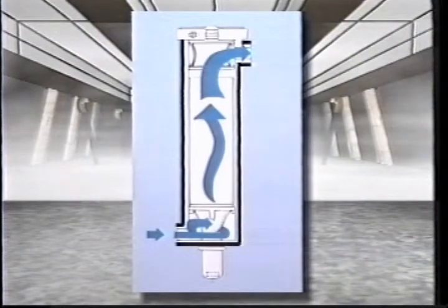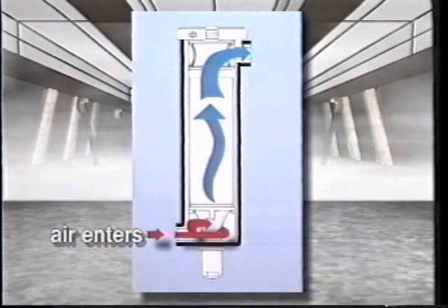Let's look at Filenco's patented air cleaning system. Air enters the lower section on a tangent and is centrifuged around an inverted cone. This action flings condensate and particulate material to the wall, where they drop into a discharge drain. This drain can be manual, automatic float, or electronically timed to discharge.